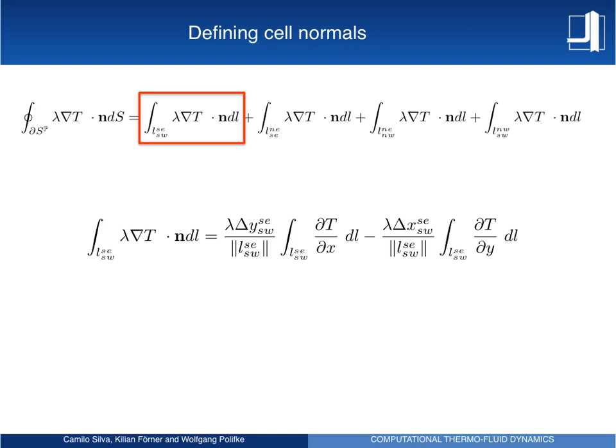So let me just draw here again the phase we are interested in. So this is the phase at the south. We have SW, we have SE, and we have the normal vector, which is NS. Well, right now I have to remind you of something. So this is the grid we are using, the grid in which we base our derivation. And now we have to have clear in our minds that these points in here, they are not nodes, okay? They are auxiliary points. The only nodes in the derivation are these black dots in here.